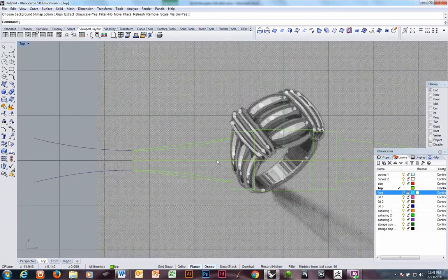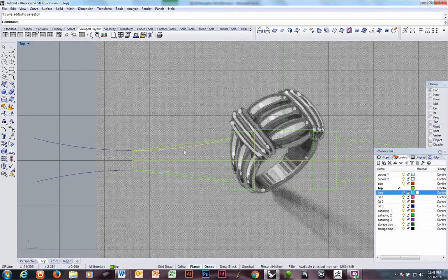Okay, so see how straight this looks and how fat that looks compared to this? We can't have this tapering that fast. So I'm going to F10, turn on the points, and back that off again, so I get some fullness.